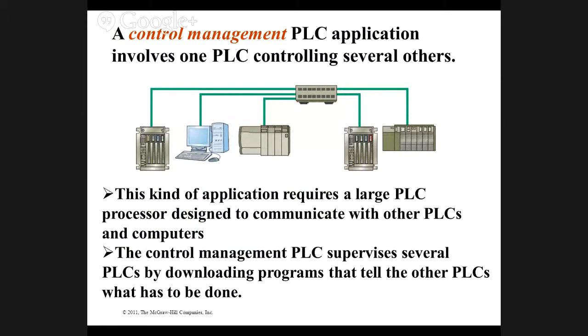I've only done these in data acquisition. One of the reasons is some people, you can make a PLC run the whole plant, right? But what happens when that PLC goes out? The whole plant's gone. So when it says control management, this is data collection to show you production values or alarms or anything on a central screen. So basically the PLC just communicates with everything and it doesn't control everything, but it monitors everything. Does that make sense? All right.